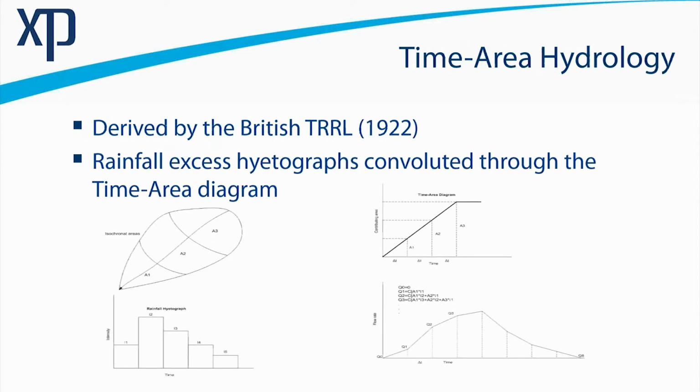Time area is another popular method, I understand, in Malaysia, although again I would likely not personally try and apply this in Malaysia. I think it has a few limitations on it in terms of particularly larger catchments, but also not necessarily flexible enough relative to the demands for detention basin calculations. So running a more rigorous hydrograph method like Laurenson's method is not only quicker, but makes assessment more rigorous.